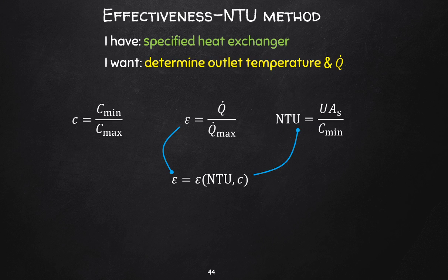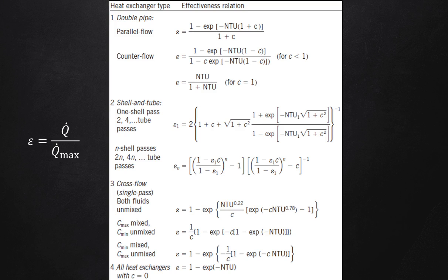With these 3 terms, they are, let's say, functions of each other. So it is possible to determine heat transfer potential for the heat exchanger in question using these 3 terms that have been defined. This method has 2 different approaches. You can either determine the effectiveness term. You would first obviously then need to determine the correct heat exchanger, which, as you can see, requires knowledge of the NTU as well as the capacity ratio C to be known.